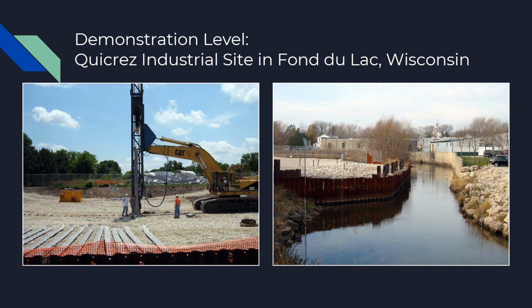Before the treatment was started, the soil was sampled and substantial DNAPL was discovered, which was found to be higher than the amount estimated during the initial design phase. Some of the areas had concentrations higher than 1,000 milligrams per kilogram. Remediation. The remediation was started with 2 anodes and 1 cathode. The installations took just 3 weeks, with the electrical and recycle plumbing taking 2 more weeks to be completed.